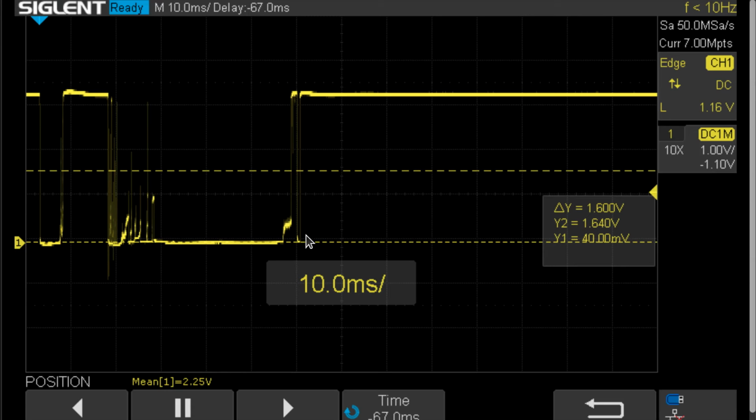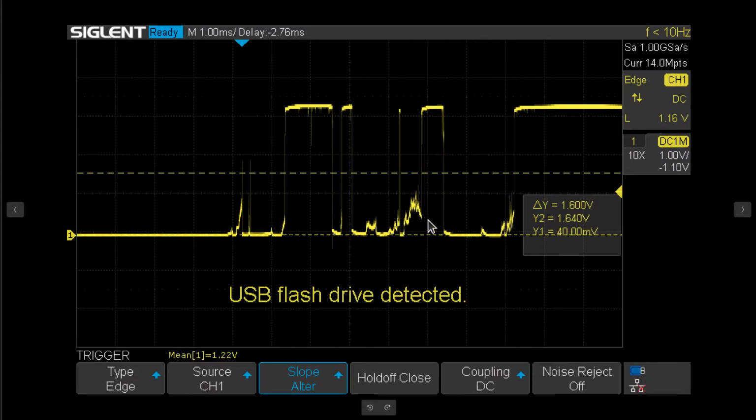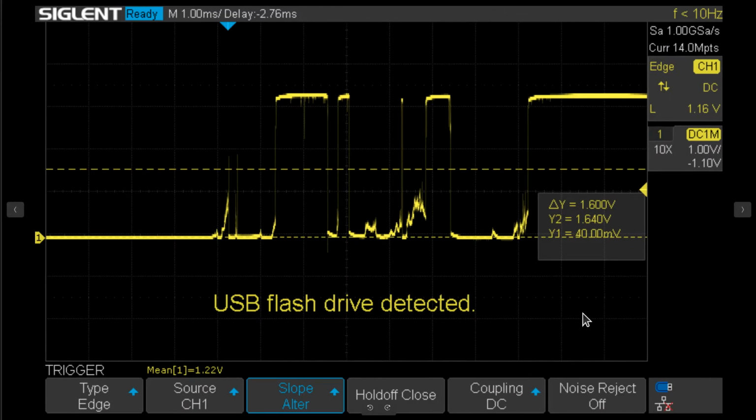Okay? So I've got a couple of other screen captures in here that I also did while hitting the button. What's my time scale on this one? 1 millisecond per period. This one's not too bad, because the previous one was 10 milliseconds, right? So what are we looking at? This is just a little bit more than 1, 2, 3, 4, 5, 6, 7 maybe. So this is actually only 10 milliseconds from the first hint of, in this case, me releasing the button.